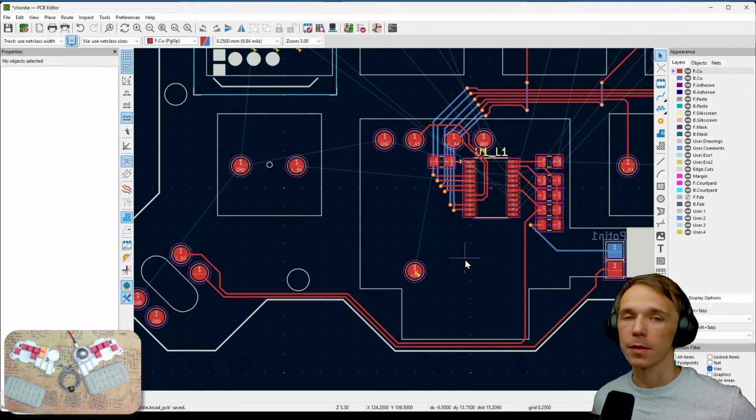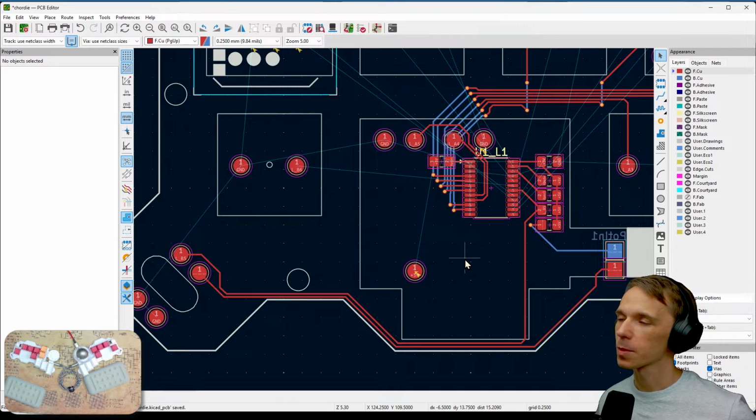Yeah, so doing a PCB is more difficult in the beginning, like you have to wire all this stuff. But then it pays off, because if you're soldering the keyboard, a PCB is so easy to solder compared to wiring. It took us, I know, 6 hours, maybe even more, to hand wire Chordie with the PCB. I think we can do it in maybe 1 hour or even less.